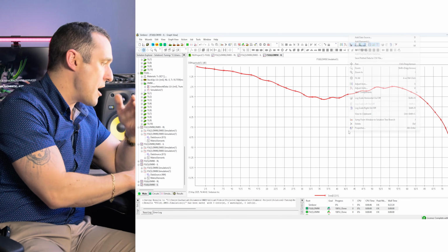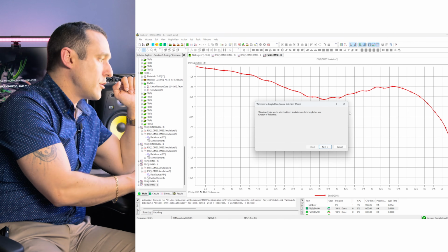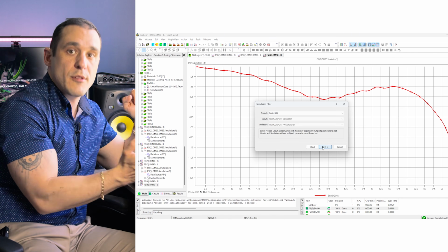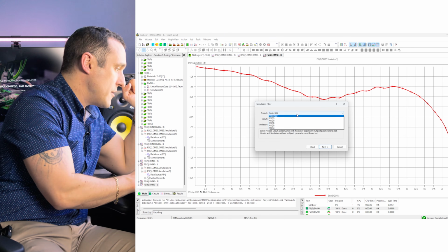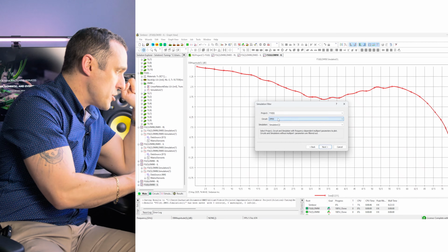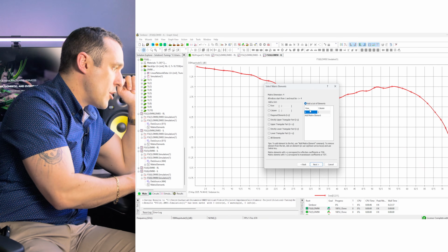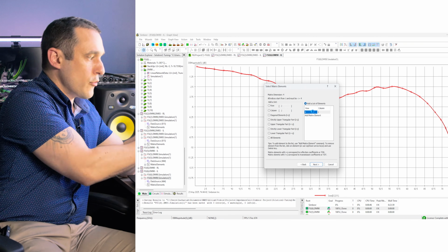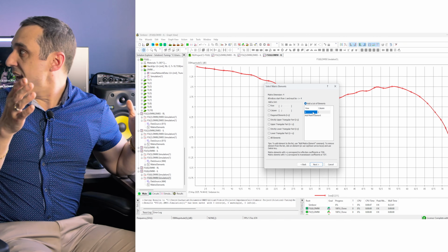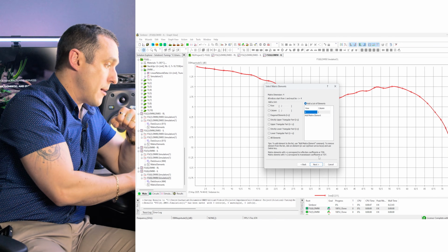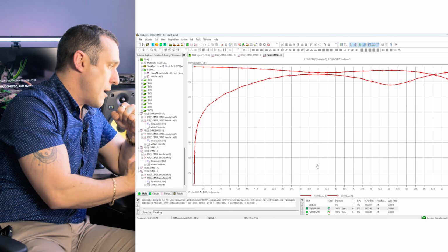So this is basically going to measure the amount of signal that gets converted to common mode noise at the output of this interconnect. So here we're just going to select the 4-1 S parameter. You can see here I've already brought in row 4, column 1. That is the SCD21 S parameter that I had on the whiteboard. And we'll go ahead and hit finish.